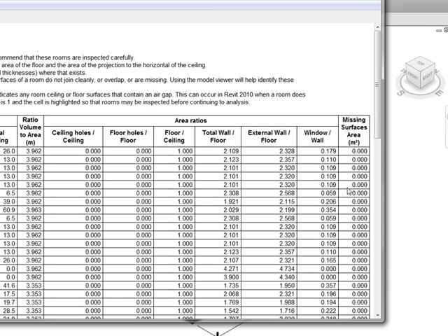Because Revit translates from the center line of a wall, if you have exterior walls where the center lines do not perfectly align with each other, previously in the gbXML we would deal with gap issues, meaning that where the center line didn't align, there would be a small hole that had to be filled in, and that exterior wall wouldn't be a completely straight line. So here in our new healing tools, the missing surface area is filled in depending on its size.